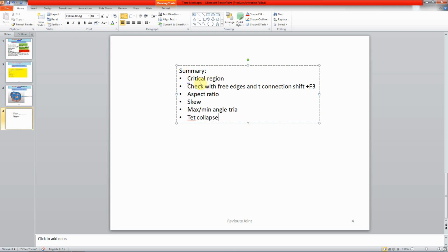Which are the critical regions, what are the bigger components maybe, what are the complex components maybe. So you can use the trick: whatever critical regions are there, you need to organize properly, and of that, first you need to mesh those properly, and the remaining planar area you can mesh easily, right?